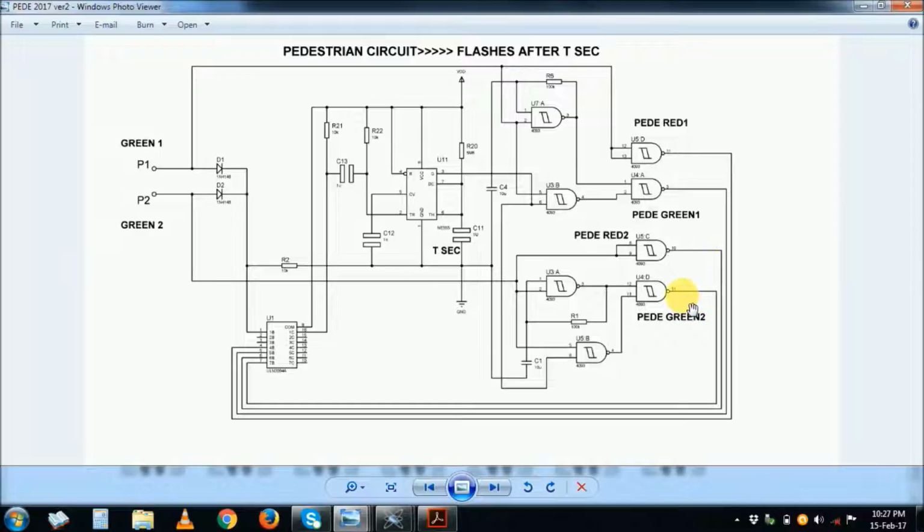So what is the condition of the green? Here you have a low. So you have a low here. So the oscillator is disabled. Here is another oscillator. So oscillator here, oscillator here. So here is a low. As long as you have a low to the NAND gate, this is a high. You have a high here, we don't know. It depends on this condition now. So we only know that the oscillator is actually disabled, it's not running. And then this low here is also coming here. Here we have a low.